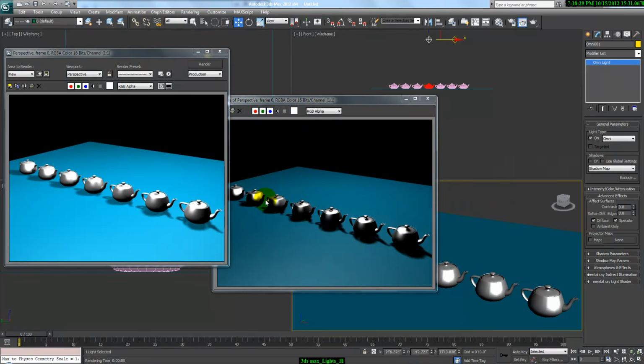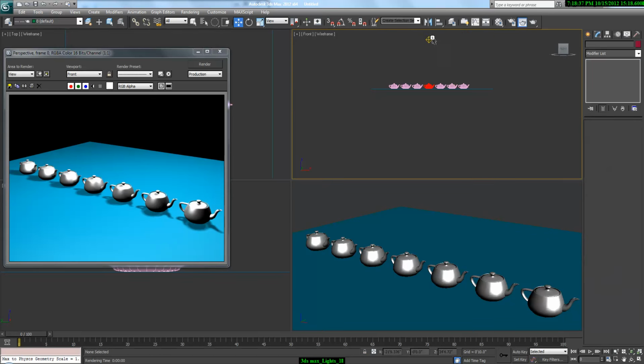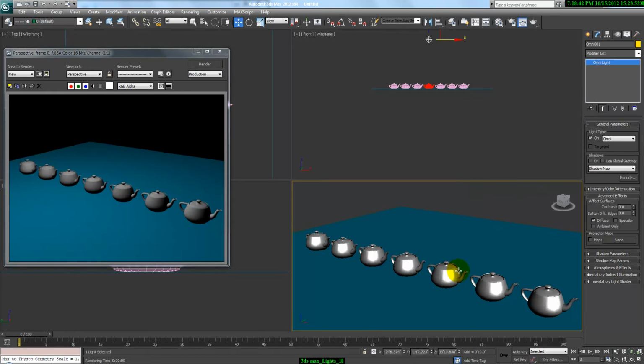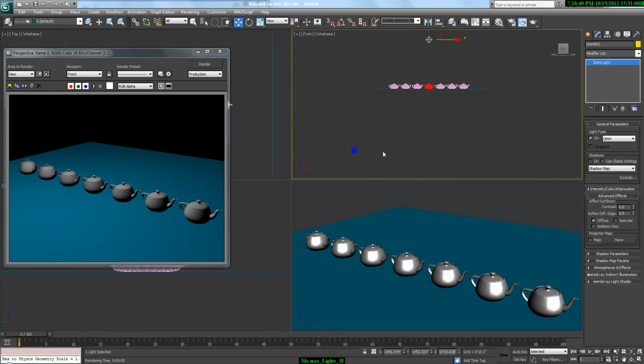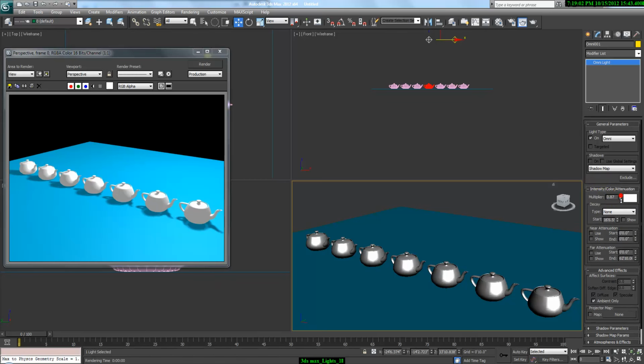And I will always tell you to compare. See, now this is the actual illumination from both the sides. So I'll just click this off for some time and I will again come back here and I say specular off. So now it is rendering but not giving any specularity. These are fillers, okay, and ambient only. Now this is the actual light illuminating and this is the ambient light. The moment I say ambient light, it will diffuse this. And the ambient light, this is the bounce light basically, has to be very low.